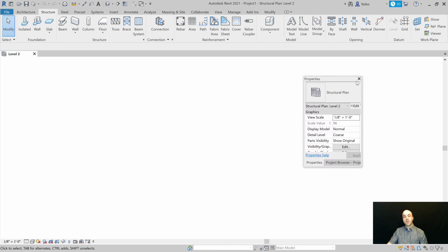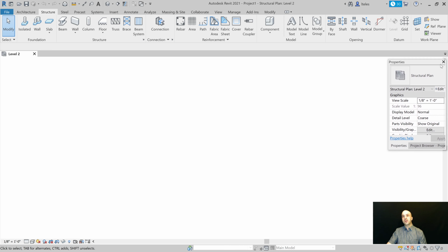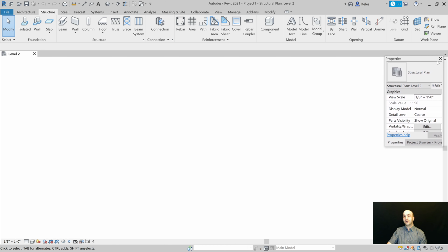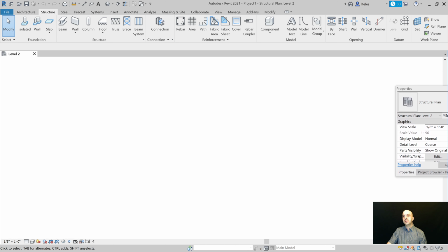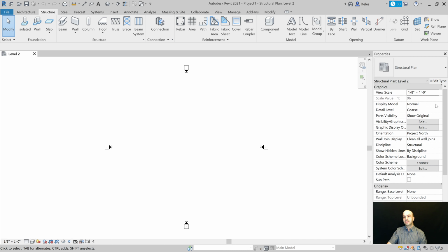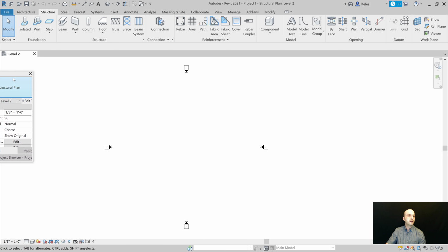Now over here on the right, Revit will dock my window based on where my cursor is, not on where the edges of my palette are. You see that I'm trying to dock it on the right, but it won't dock. I have to pull my cursor all the way to the right until it'll actually dock. There you go. Alright, so I'm going to move it back over so that my camera doesn't interfere. And you may have to finagle a little bit.